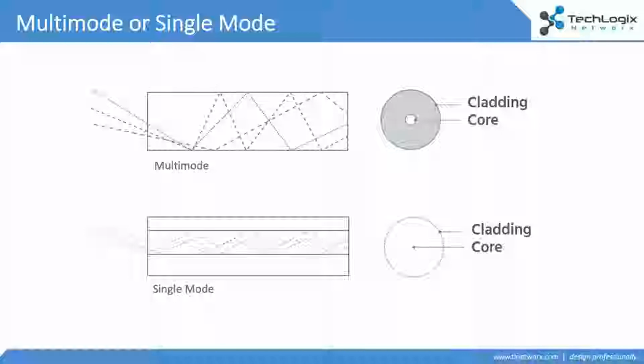That's the easiest way to differentiate these two cables when you're starting to design your different installations. Single mode over 1,000, multi-mode under 1,000. Now, you can certainly use single mode under 1,000 feet, and actually in a lot of commercial applications, data center applications, it's all single mode.